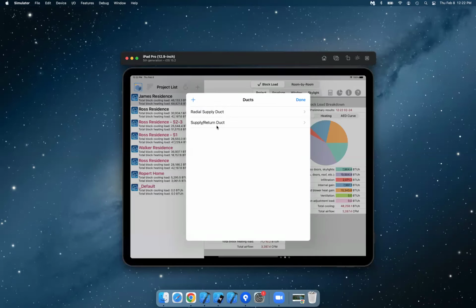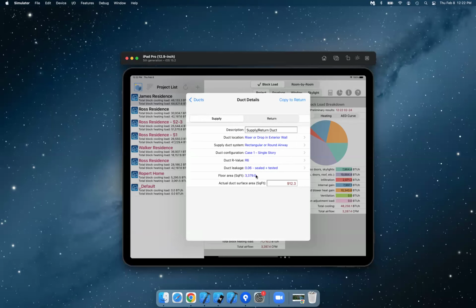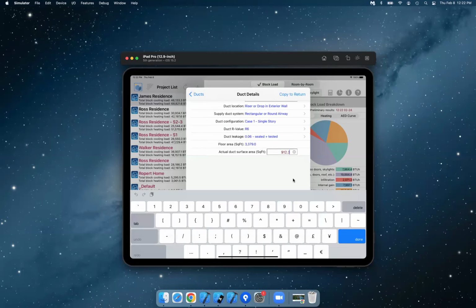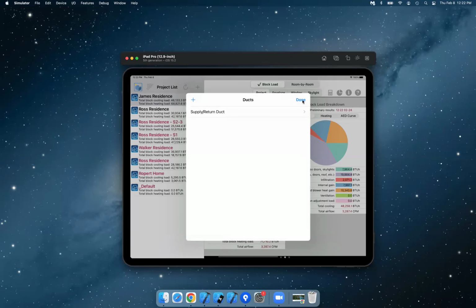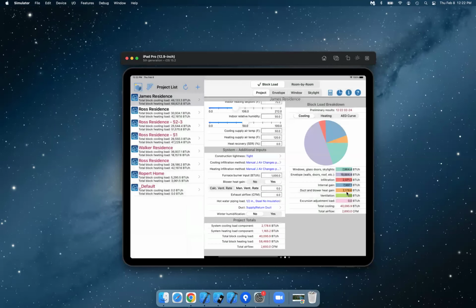So let me go back here. And I'm going to delete. You can actually have multiple systems. I'm going to delete this one. Just keep things simple. Let's actually go down to say 200. And let's go back. And you can see now that I'm down to 1,002 per hour. So much more reachable. So you kind of have to play with these numbers a little bit, especially if you have a duct system that potentially could be leaking a little bit and could add to your heat loss and heat gain. Any questions about this?